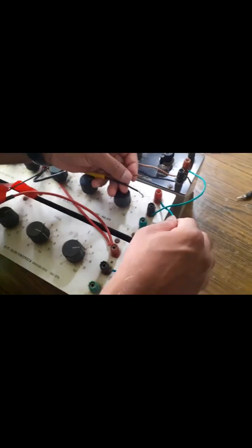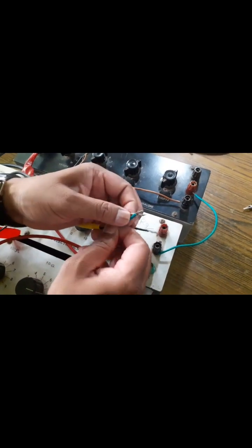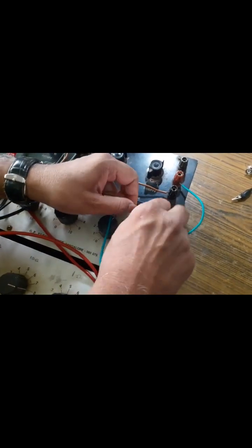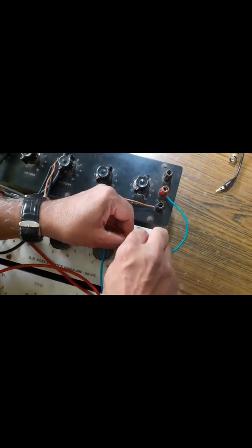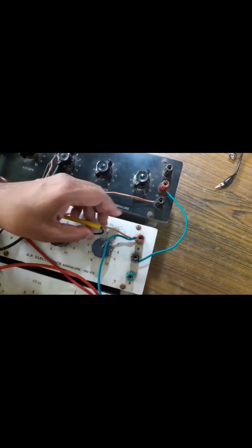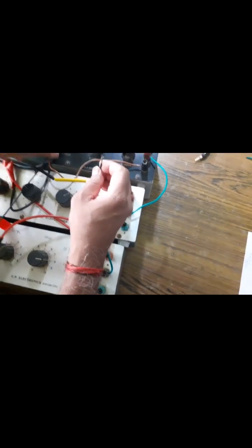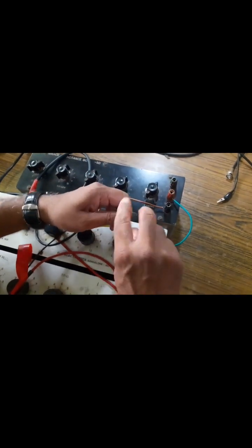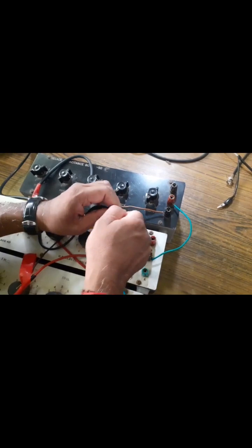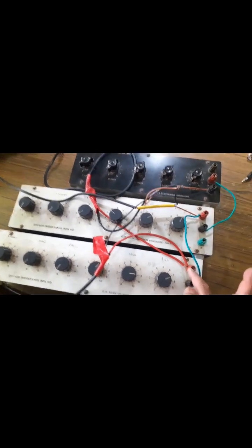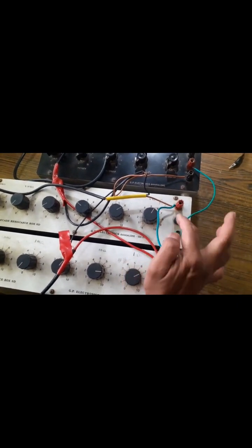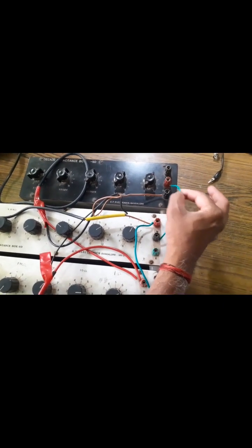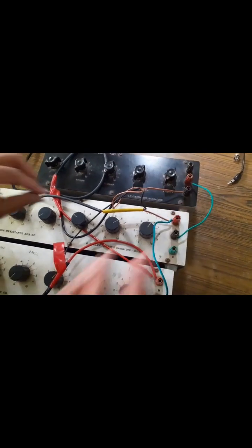Okay. So in order to observe the output on the CRO, I am connecting the CRO probe to the junction where R1 and R2 are meeting, and the other end obviously should go to the reference point. Right. So the circuit connection is over. It is very simple. Start with R1 to which the input is fed. The other end of R1 should go to R2. The other end of R2 should go to the capacitor positive terminal. The negative terminal of the capacitor should go to the reference point.